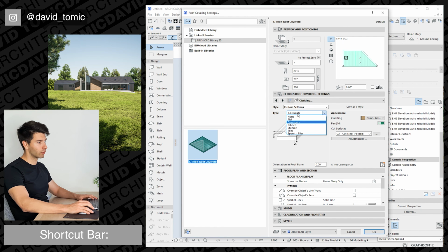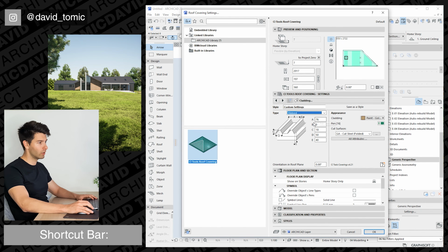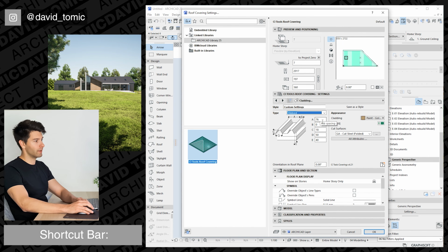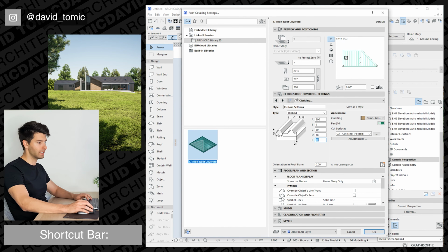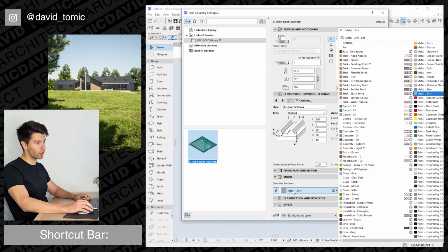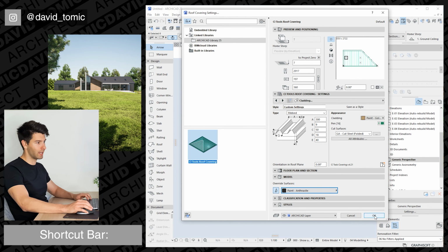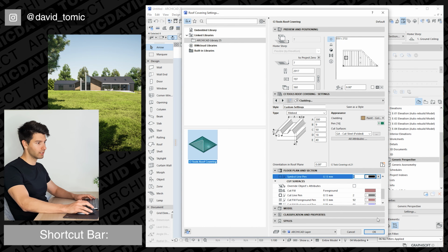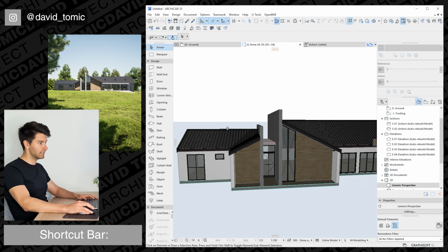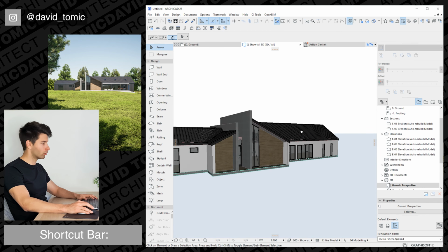we are basically going to click through, go from our corrugated to our ribbed, and we're going to just change some of these settings. So A is going to be 300 millimeters, B is going to be 9 millimeters, D is going to be 18 millimeters, C is 50, and we're going to call E 40 millimeters for now. That's absolutely fine. I'm going to click on my model, override, and I'm going to paint that the same black color. Same with my floor plan, override all the colors, straight black, okay. And now we have our roof cladding created.